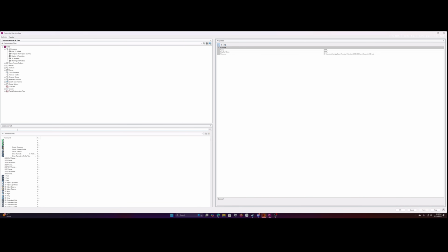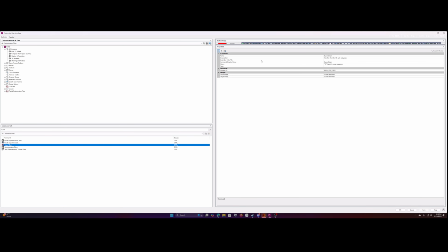So what we're gonna do is go down here to our super clean, and go over here, and fix our macro. So here we had our audit, semicolon Y, semicolon. We know that the first portion worked. Next, it was -purge, right? And then we chose regapps. But after this, it was an asterisk, right? And then enter. And then it was verify name to be purged, no, semicolon.